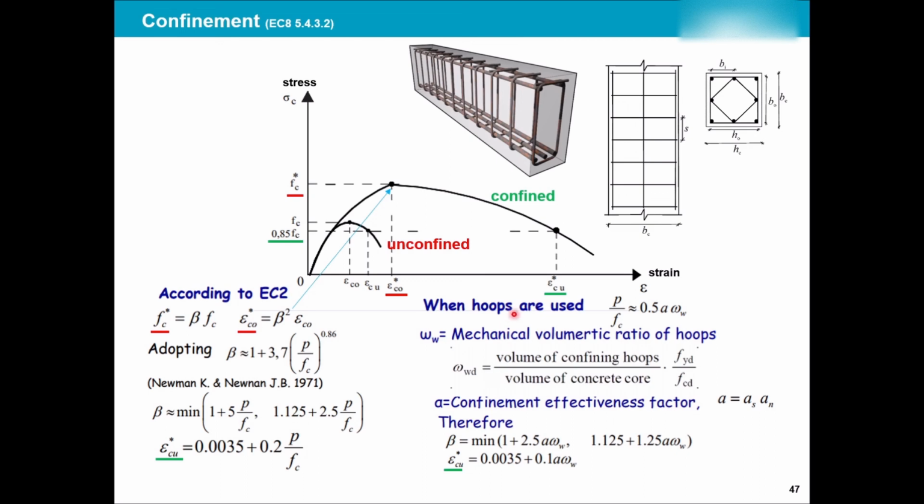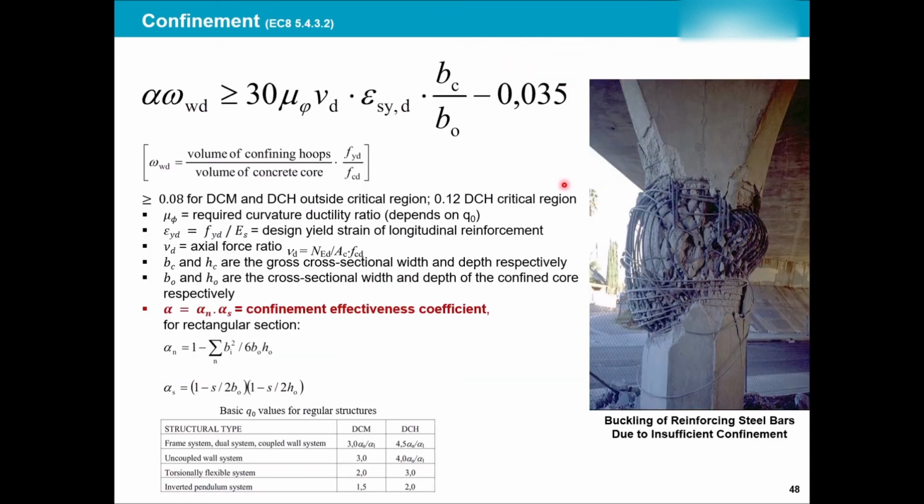So again, Eurocode has some formulations to make sure that you reach that confinement and your concrete becomes something similar to this. The last formulation that you have to check based on Eurocode is the confinement effectiveness coefficient, alpha. If this alpha is satisfied, your confinement is good. This long formulation is always the end point of your calculations. If it is not satisfied, this will happen.